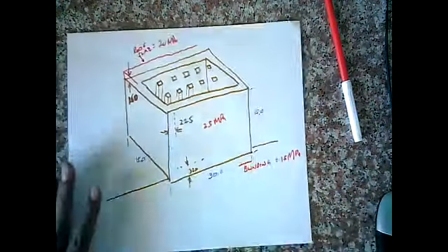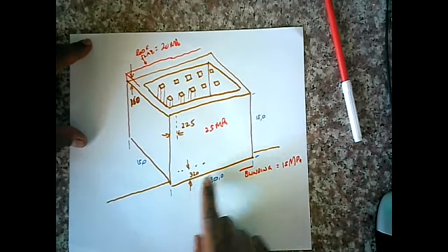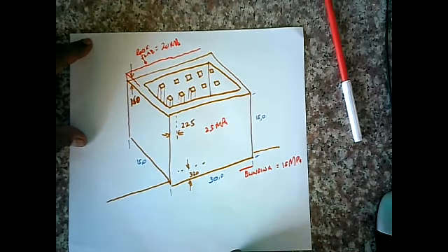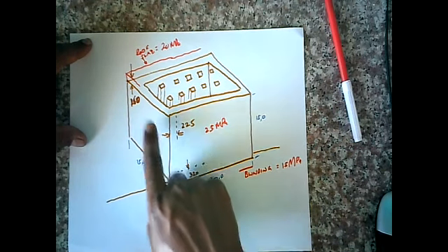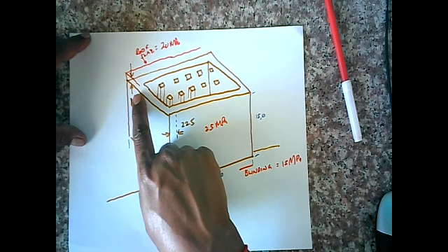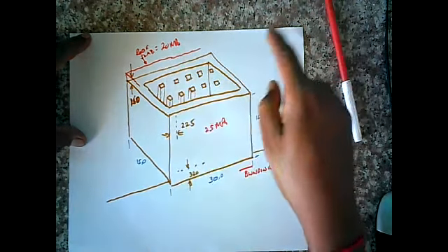Now let's try and understand this practically. Okay, so here's something. Here's a floor thickness of 320, partially in the ground. All right, the walls have a thickness of 225. The roof slab is 160, also at 20 MPa.